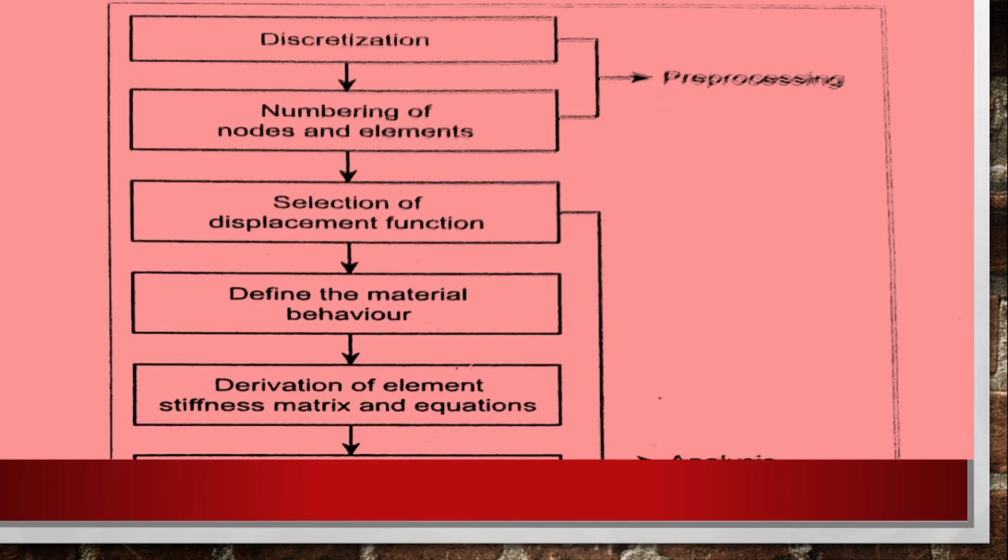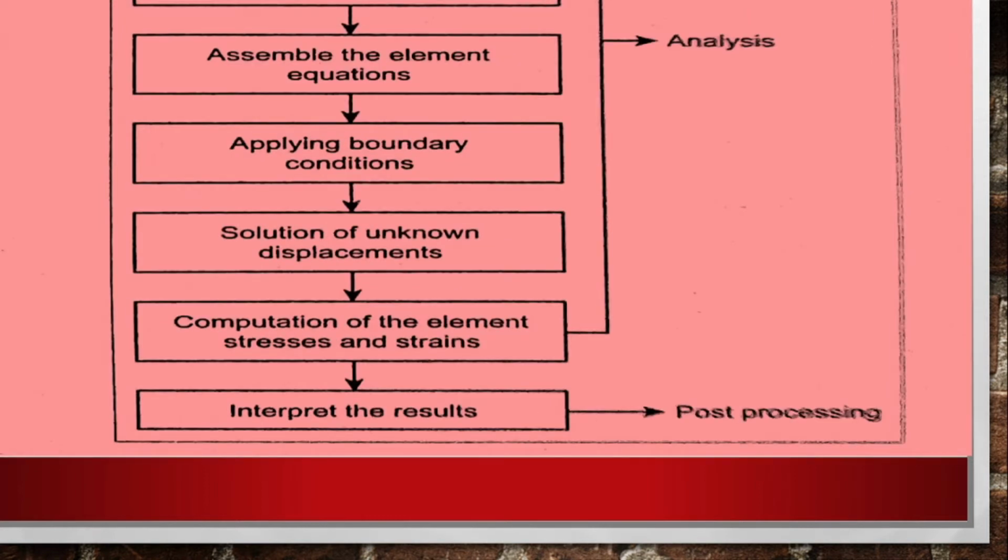here are selection of displacement function, define the material behavior, derivation of element stiffness matrix and equations, assemble the element equations, apply the boundary conditions, solution of unknown displacements, computation of the element stresses and strains.